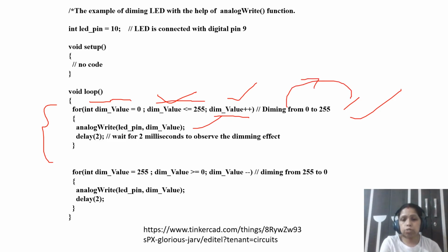And this is for turn on to turn off, here also to decrease the intensity. In this case you can increase the intensity, and in this case you can decrease the intensity. So within the bracket, in dimValue, here in this case it has already reached 255. Now you want to decrease the value, you need to reduce the brightness.